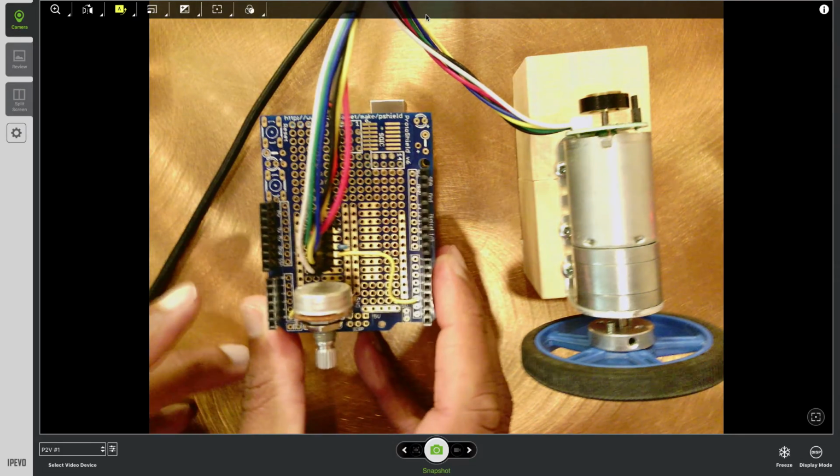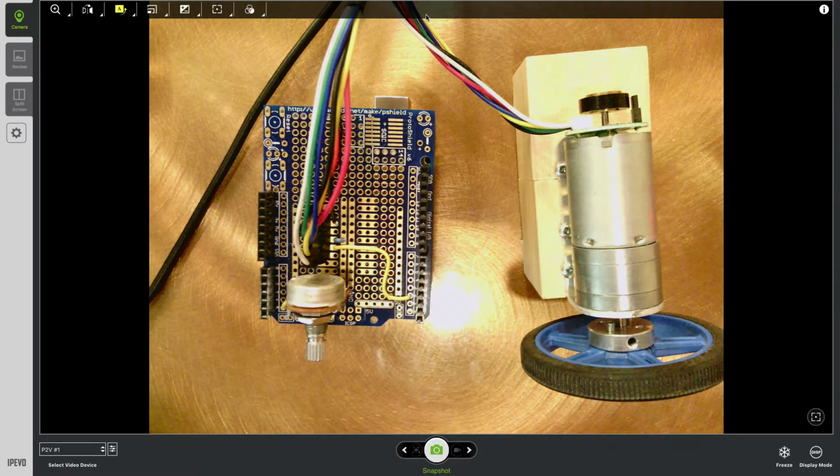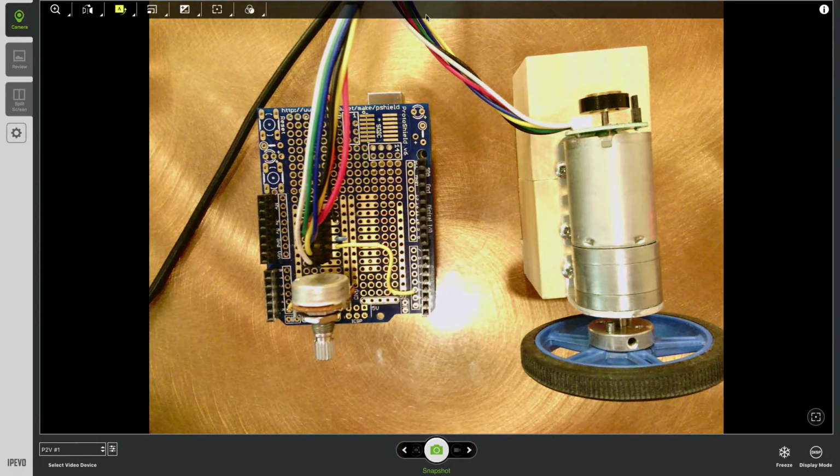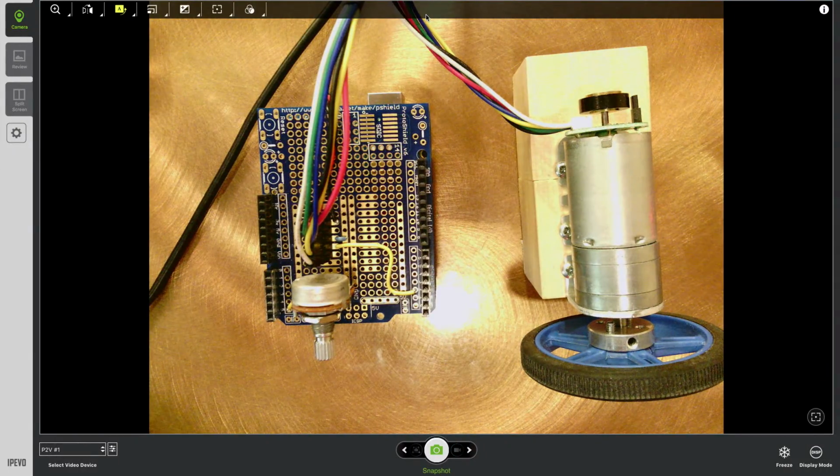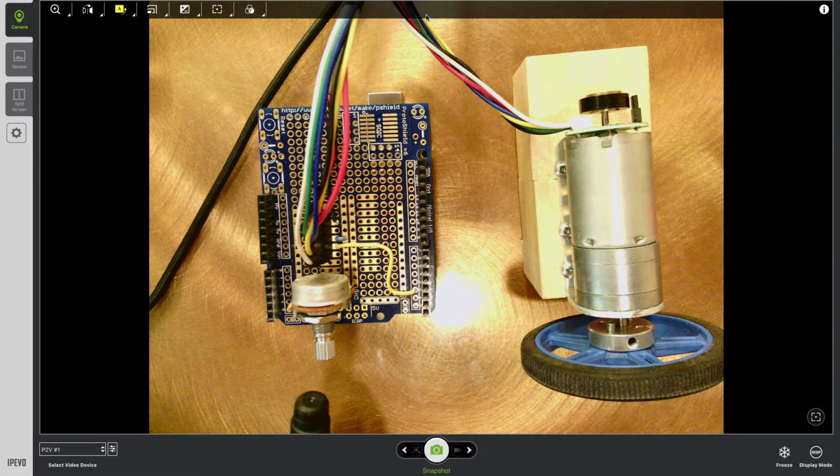The reason I have that motor shield is to boost the power of the signal that is coming from the Arduino. During operation, the motor will be drawing much higher power than the rated value of the Arduino pins. Okay, I can show it from here. So I'm using this potentiometer here to set the reference speed, the speed I want the motor to be turning at.